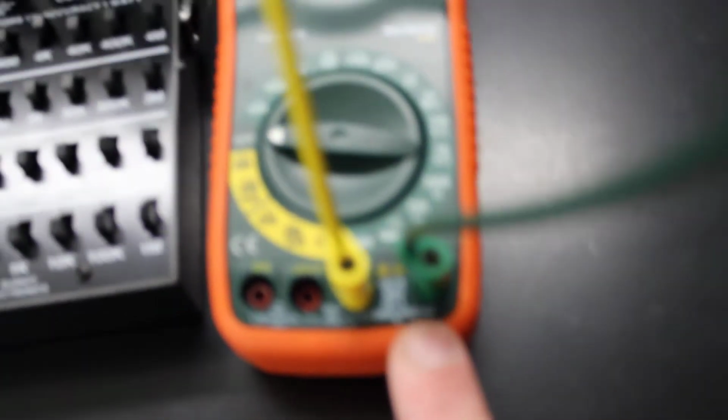Great. So now we're going to measure the resistance of the resistor. So here are the two ends of the resistor. We put them into the proper inputs here of the multimeter. Turn the multimeter on to measure resistance, and I get a reading of 3.98. That's kilo ohms. So 3,980 ohms is our resistance, and that'll be recorded on the data sheet I sent you.